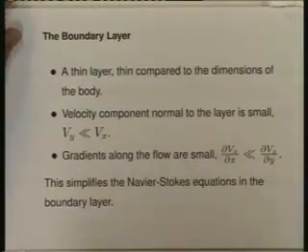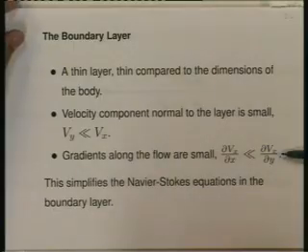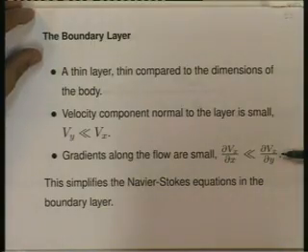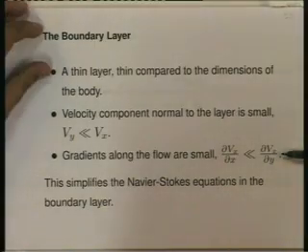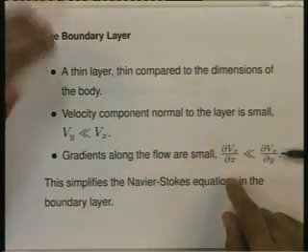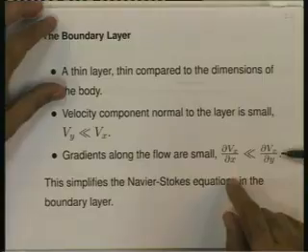The third characteristic is that the gradients of any variable, x component of velocity, y component of velocity, even pressure, along the direction of flow are small compared to across the direction of flow.